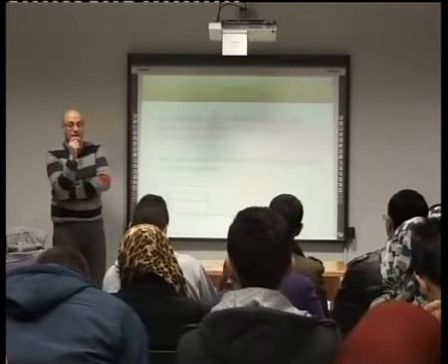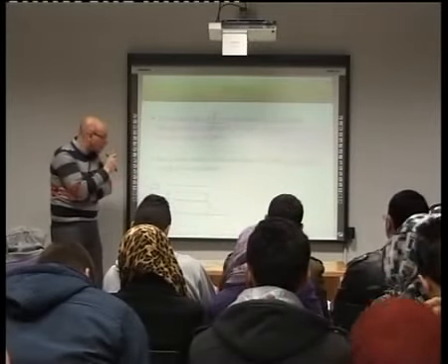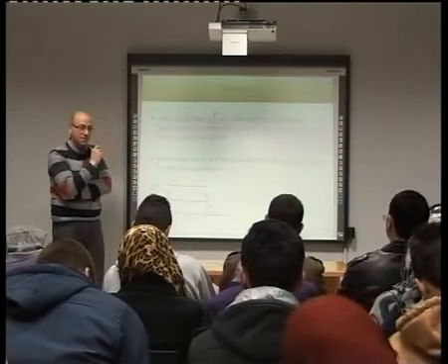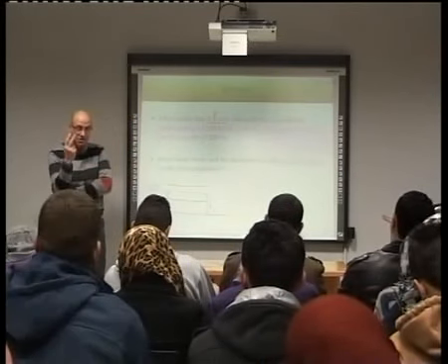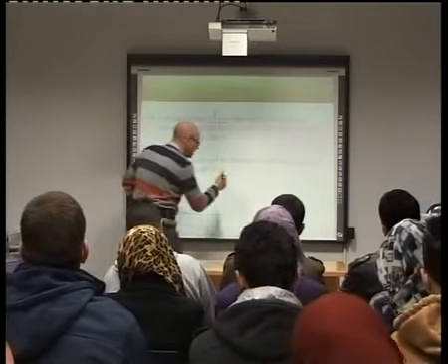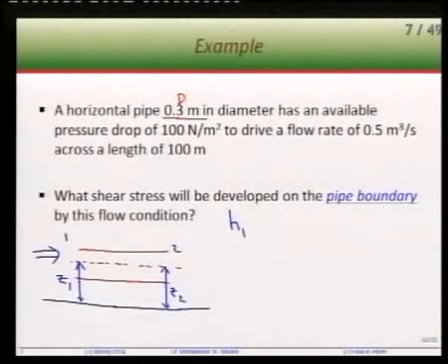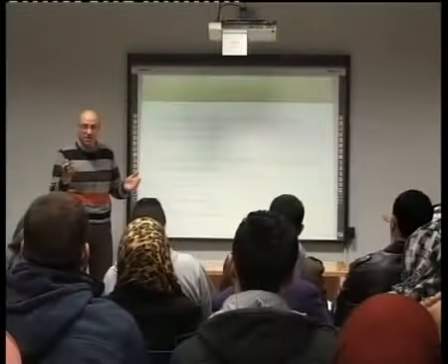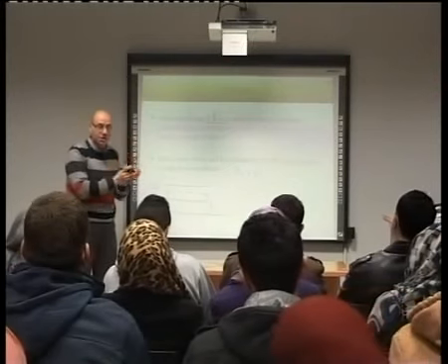Now, why am I not saying a higher total head? For two reasons. Again, generally, don't make that mistake. Generally, we must say H1 is larger than H2, and the head loss is the difference. But because this is horizontal, we dropped delta Z. And because this is uniform, we dropped the change in the kinematic head.